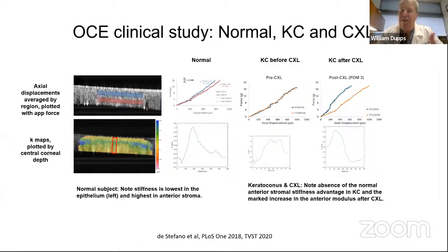So now we have a contact force and we have a displacement. And if you just in your minds flip back to Vinicius's very first slide about measuring mechanical properties, a force and a displacement or a stress and a strain ratio can give you something analogous to a stiffness or a modulus. And so that's what we're doing here. We're calling that value K. We're not going to claim it's exactly the elastic modulus, but it is related to it. And what we can see here is there is a depth-dependent profile in that stiffness value.